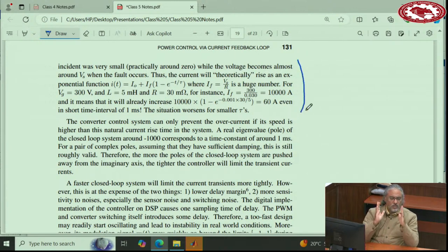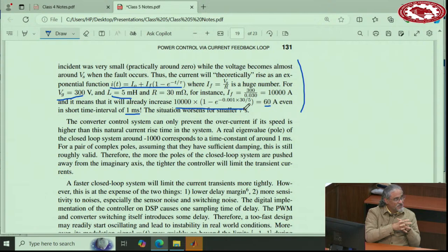Let's say the converter is operating in normal condition connected to the grid, right? So this is the grid and this is the converter, the voltage of the converter. So these voltages are very close to each other and the current is flowing. But these voltages are very close to each other because the resistance is small. Now let's say this grid voltage instantaneously or transiently drops, because we cannot really make it fast. Right? One solution is you need to increase the switching frequency to 10 kilohertz now. If you increase it to 10 kilohertz, probably you can address this one.